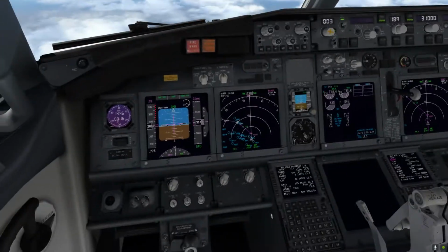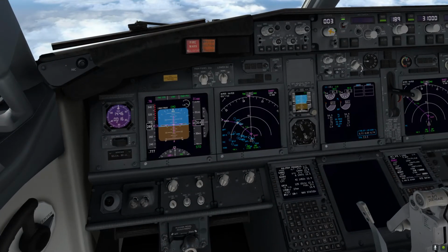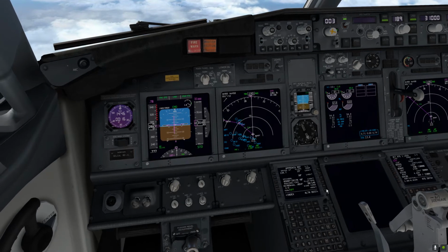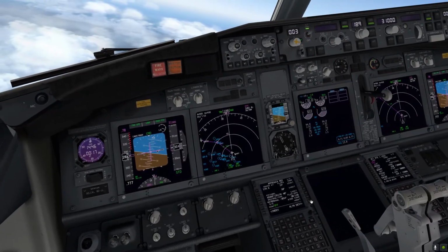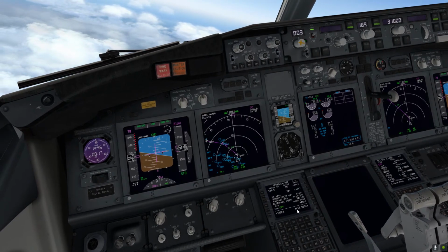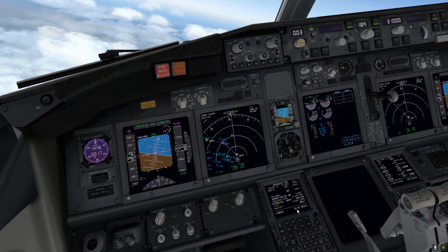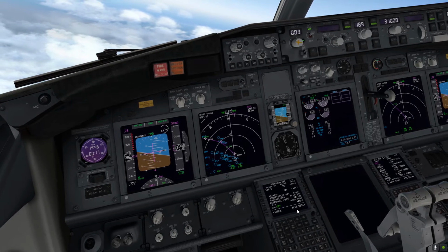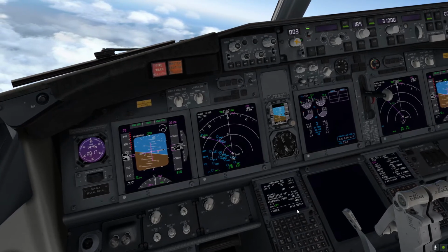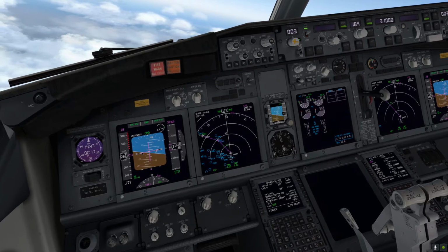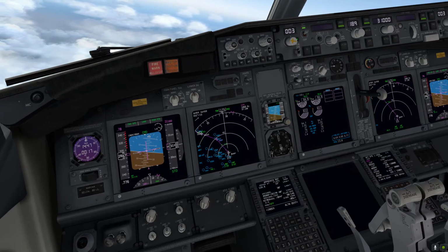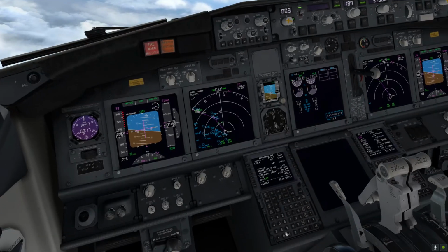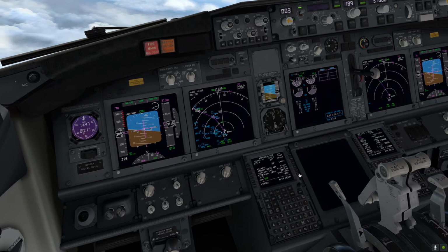And to go ahead with the preparation for landing, we just expect to use auto brake 3 and flaps 30 with some kind of standard wing correction. No, definitely not standard wing correction today. Not today. Now we have like gusting 25. So let's see. Yeah, like plus 7 knots sounds good to me today.